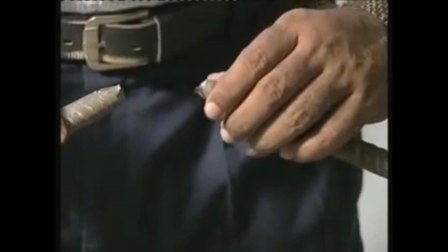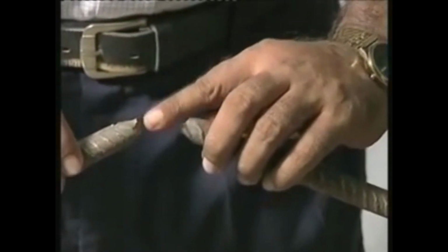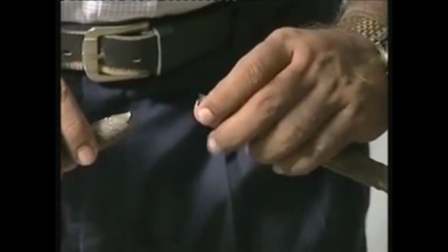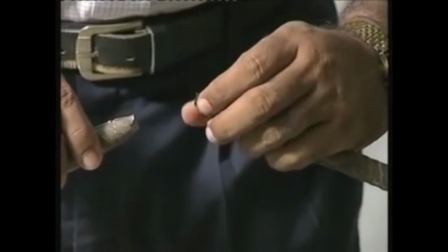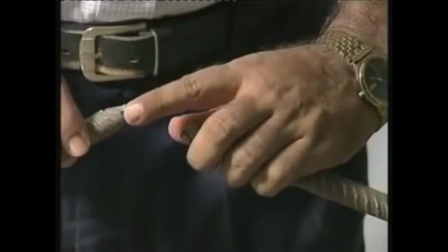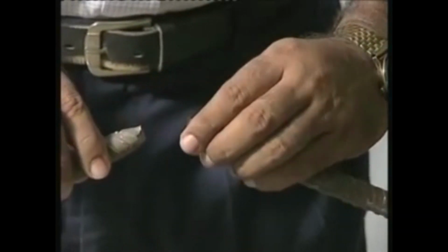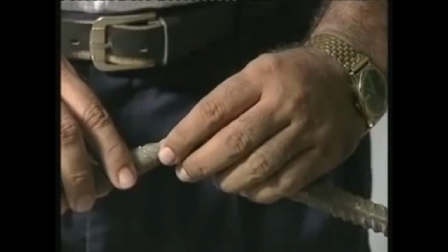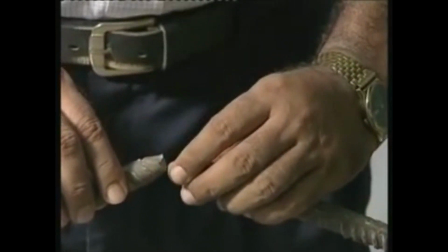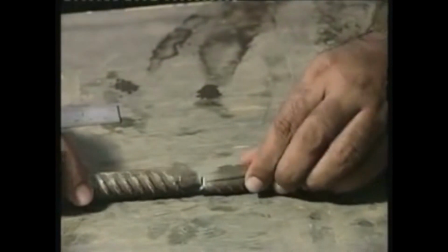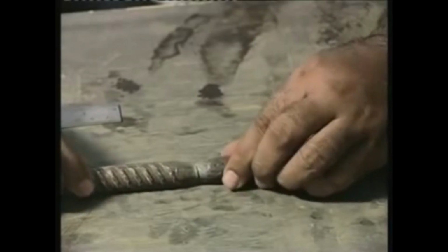After the bar has been tested, if we look into the failure of the bar, we will see that one side has formed the shape of a cone and the other side is that of a cup, and this kind of failure is generally called cup and cone failure. Now, if we look into the whole length of the bar, you will find that at the central part it has undergone extension, and because of plastic deformation, the length has been extended.